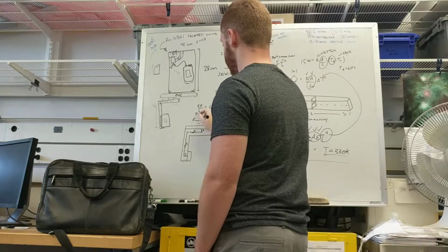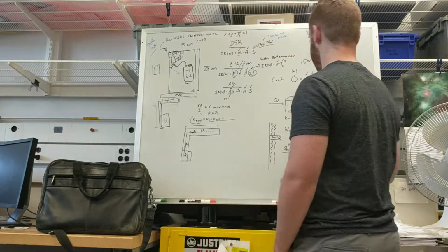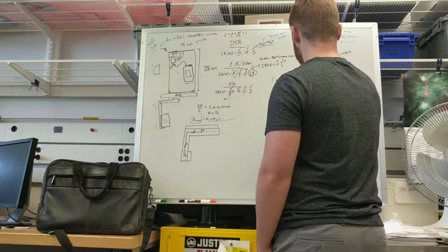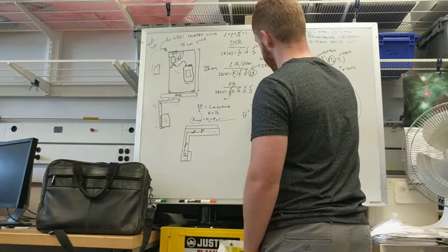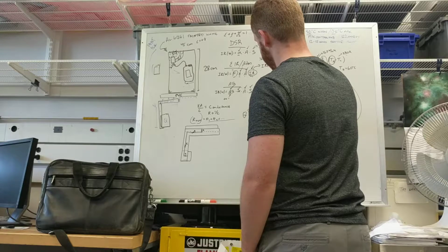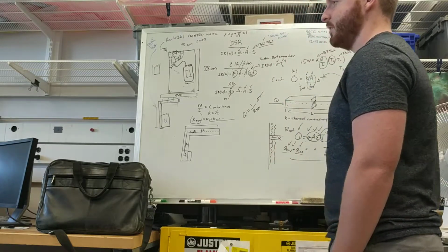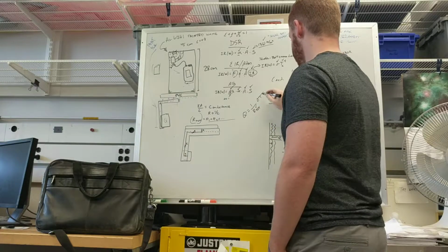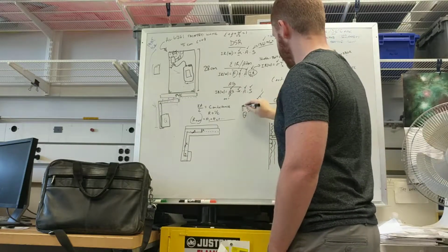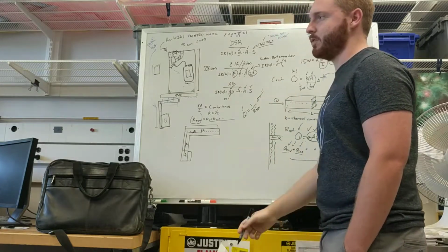Then you can plug your R total in here, because your kA over L is just 1 over R total. So you can rewrite your equation as Q equals 1 over R total times delta T. You can compute your series resistors, this is now known, you can grab that T from down there, and you can still find your electronics temperatures through that path.